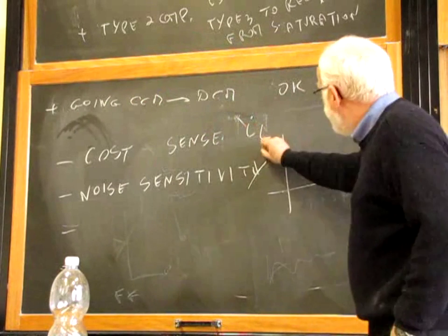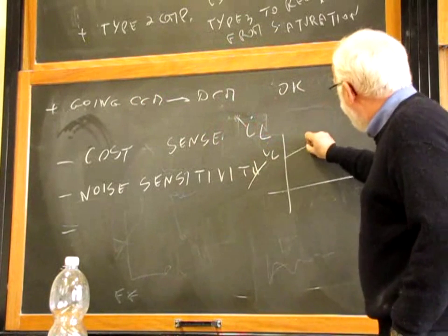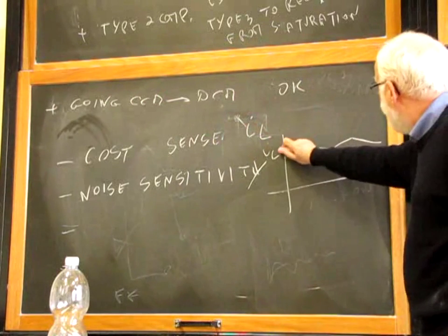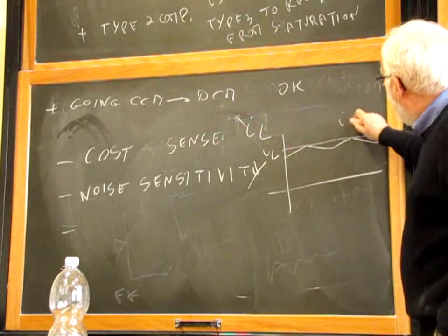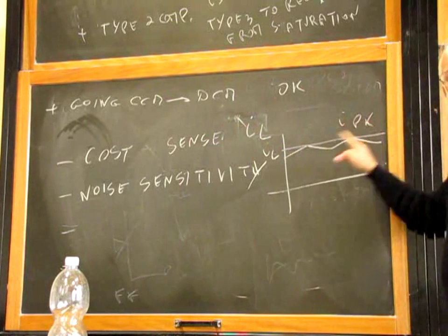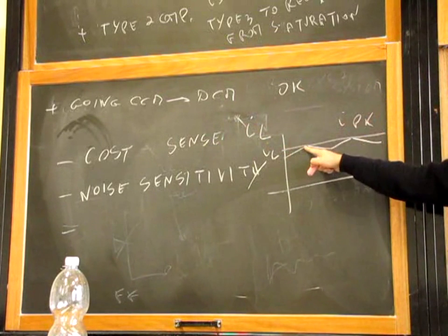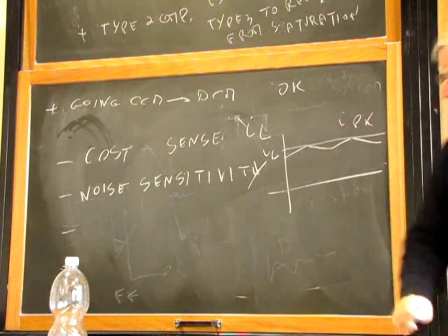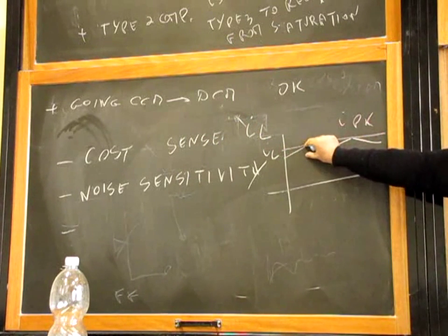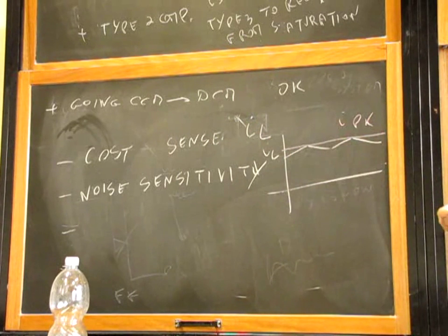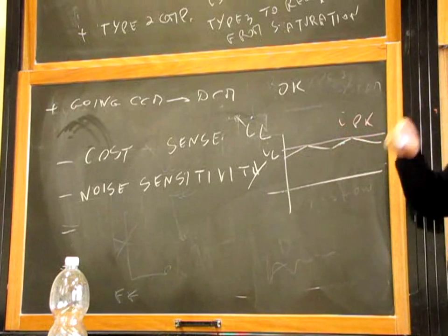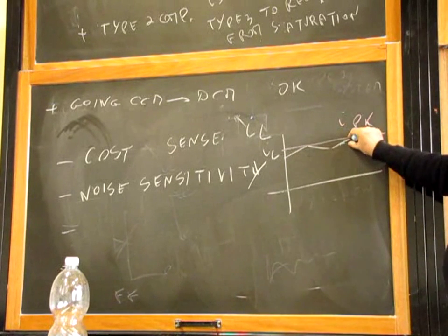Because, look, IL is something like this, and it's working with this IP. You control this IP and your IL ramps up till it reaches IP, comes down, ramps up and comes down. But this ripple is small because we are working in CCM, deep CCM. So if we have any noise, for example here, a small spike, a small noise that goes here, there are 2 millivolts here.